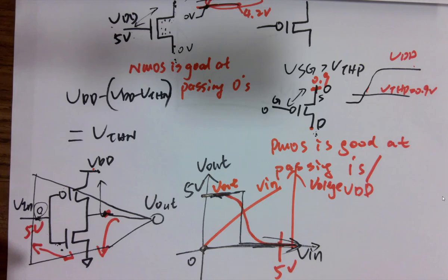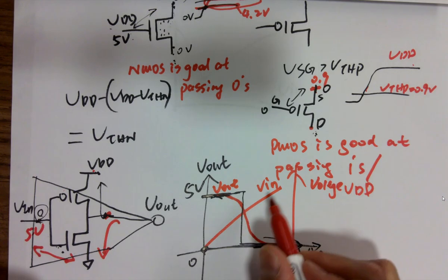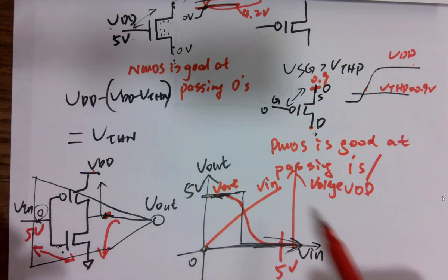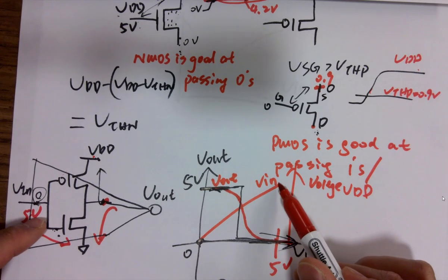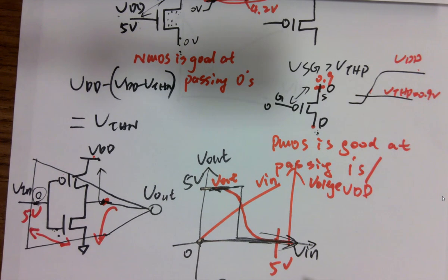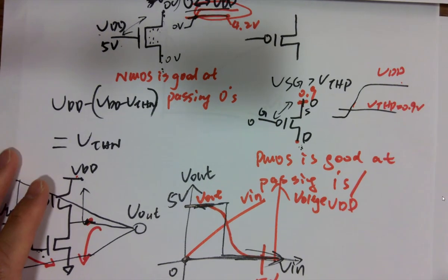Okay? VN is your input, it's not dropping anywhere. But it could be a digital signal. If I'm giving a linear DC sweep, you are seeing this. Should I give it a pulse? Yeah, I can give it a pulse, right? Because the input of the inverter can be an output of something else. So it won't be a perfect linear voltage. It could be a pulse.